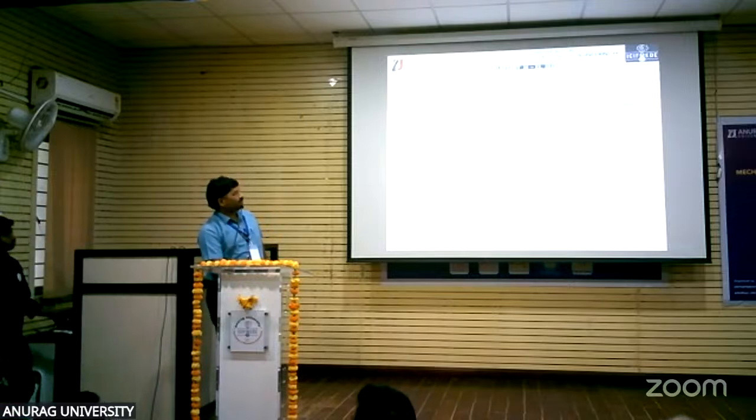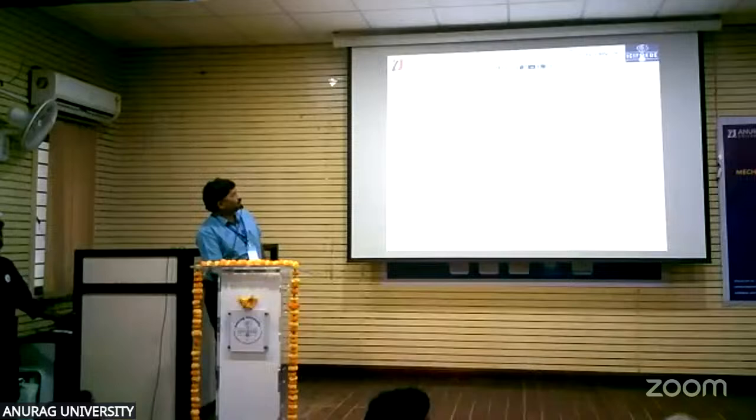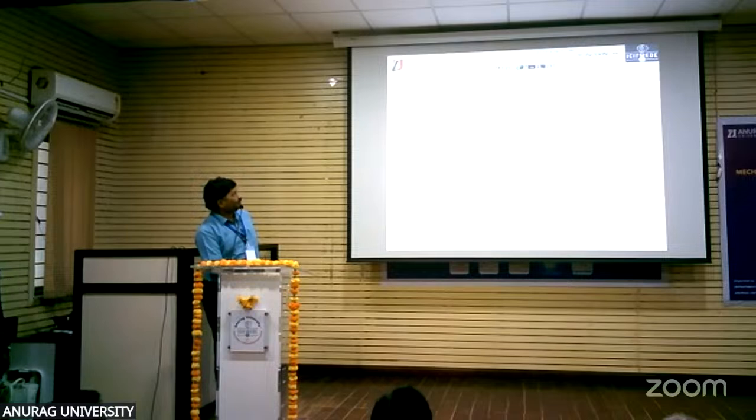For our paper, the objective is to optimize ultrasonic welding parameters. Here the parameters are pressure, weld time, and amplitude. We optimize them using teaching learning based optimization, and I compared TLBO with the Taguchi method and GRA.